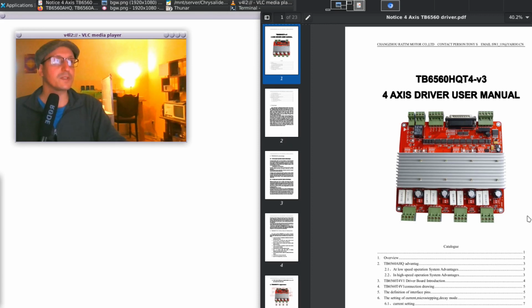Now I got an issue with this board. First of all, the channel for X burnt when I tried to measure with a scope, and the ground probe shorted 2 of the pins. Instantaneously, I had a short circuit and channel failure on the output. I configured X to be on the 4th channel in software, and I could use the CNC machine again.